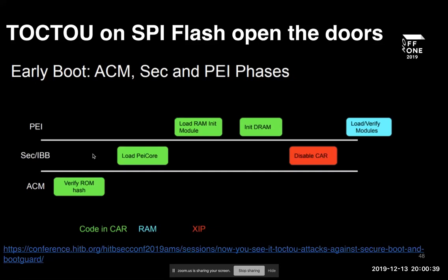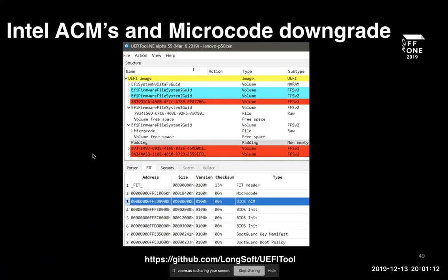But sometimes they do it just once and do not check it during other boot phases. Basically, we're talking about the fact that if it was authenticated once, that doesn't mean it can be trusted forever. For example, if you check at the very early stage and then don't check and just trust it in the later phases of the boot process, it can be faked. And we will cover this part too.